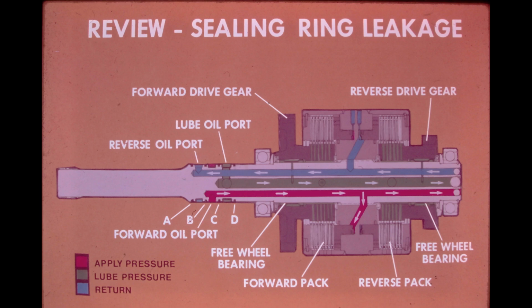The answer to number 3 is B. If both forward and reverse are affected, the sealing ring between the forward and reverse oil supply ports is the only one that could be the cause of the problem.